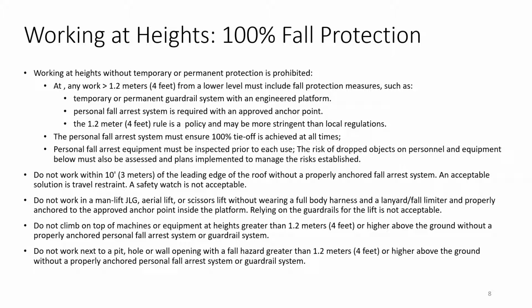risks. Do not work within 10 feet or 3 meters of the leading edge of a roof without a properly anchored fall arrest system. An acceptable solution is travel restraint. A safety watch is not acceptable.